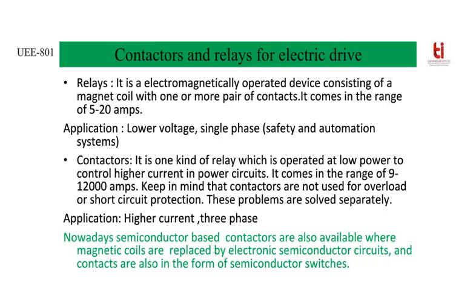The reason behind it is that the switches are very fast and available in a wide range from low power to high power applications. High power thyristor, low power transistor or MOSFET, and for medium power you can use IGBT. Another advantage is that the switches are highly reliable, highly efficient, the cost is very low, and they can be controlled easily by providing suitable pulses across the base or gates of the circuits.